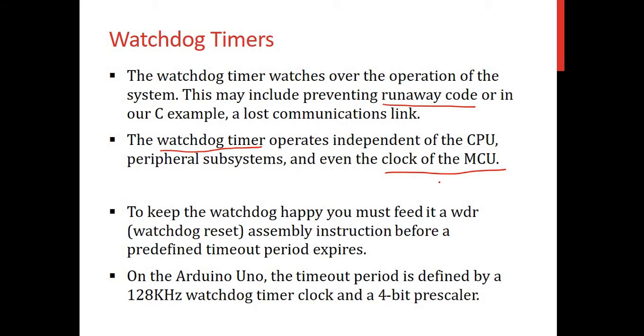As we know, the Arduino has multiple clocking options, and the one our Uno board has by default is the 16 megahertz. Different boards may have different clock frequencies, and you may also choose other internal clocks to run your microcontroller on. But the Watchdog timer has its own independent clock.